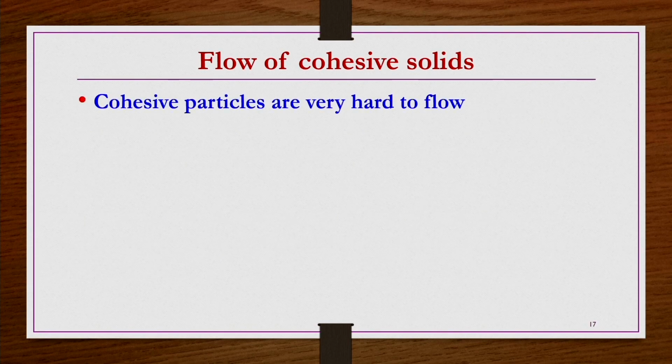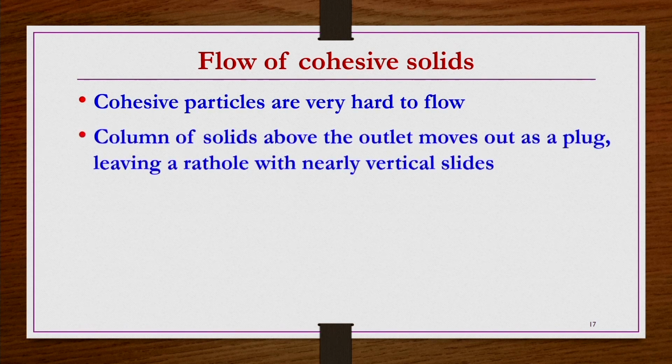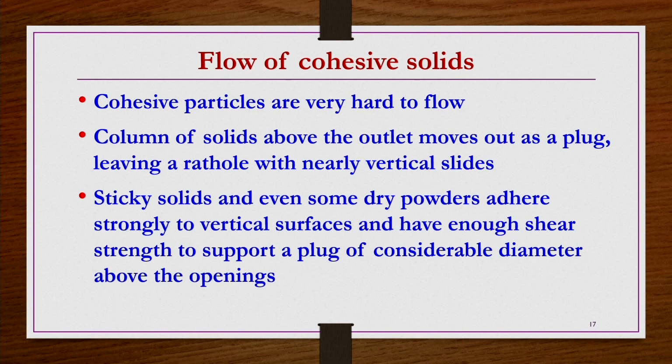Whereas in the case of cohesive solids, flow is very difficult to maintain, because a column of solids above the outlet moves out as a plug, leaving a rat hole with nearly vertical sides, as we have seen in a funnel flow pattern. That especially happens with cohesive solids. And sticky solids and even some dry powders adhere strongly to vertical surfaces and have enough shear strength to support a plug of considerable diameter above the opening.